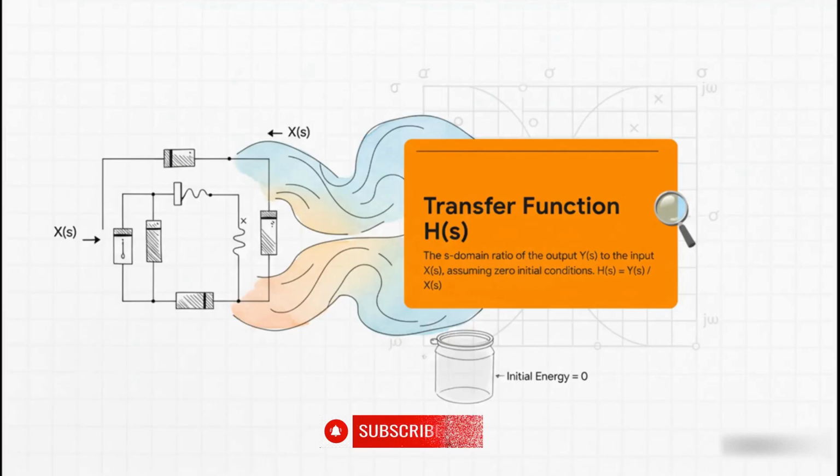And the key idea for doing this is the transfer function, or H of S. All it is, is a ratio: the circuit's output divided by its input, all in the S domain. You can almost think of it as the circuit's unique fingerprint. It describes how that circuit will respond to any signal you give it, assuming you start from zero energy.